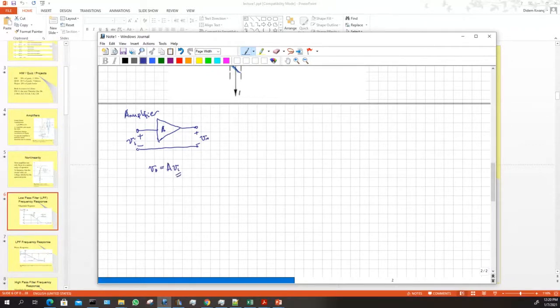Very important. You have a small input to your system, a small tiny voltage coming from your sensor. You need a larger voltage so you can measure it properly using your A to D converter and get it into your system. So you're going to need an amplifier, right? The TV doesn't pick up a signal, you amplify it so that it can recognize that signal. It can catch on to that signal.